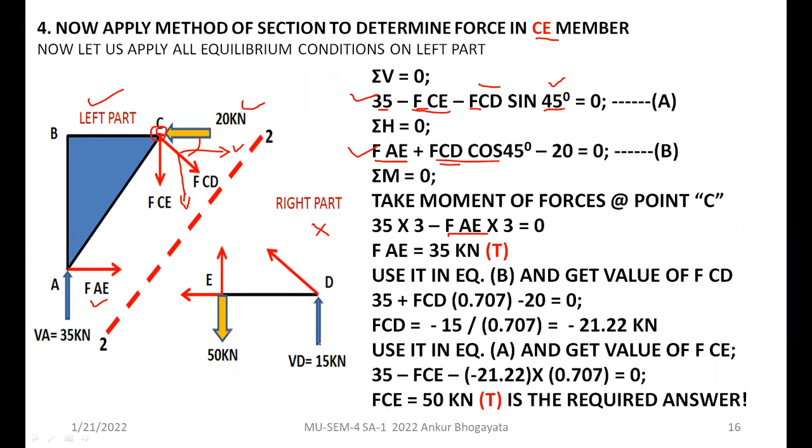Don't worry about it also. Let it be whatever. So on the left hand side, now we have 3 points, point C, point B, and point A. So if I take moment about point A, I will have to see moments of unknown forces, which will not solve the purpose, because I have 3 unknown forces, 1, 2, and 3 here. Of course, I can take their moments, but it will not solve my purpose, right?